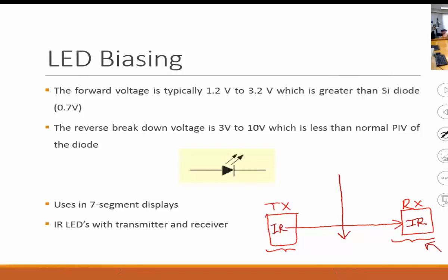Robots can also be walking around, and if you step in front, it wouldn't even slow down without such sensors. So yes, there are a lot of applications for these. Some of these applications you will learn down the line, and probably build some applications with it. There is a course where you will use infrared exactly like this, positioning them opposite to one another. Depending upon how much power you are transmitting, the distance will vary, so that is how close you need to place them.